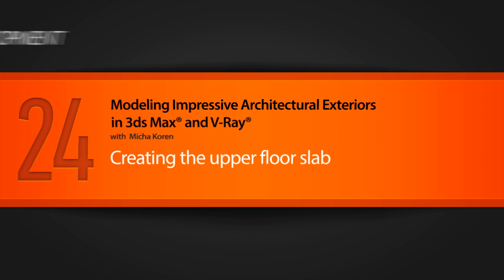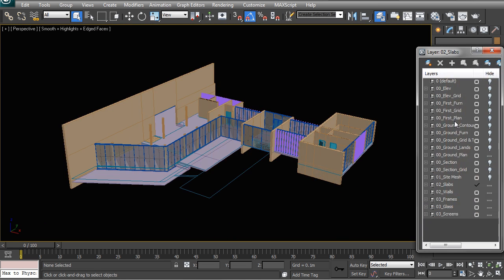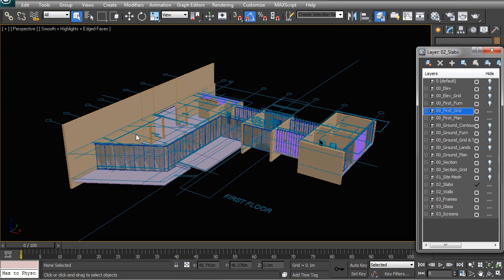In this lesson, we're going to be modeling the first floor slab from plan. Now, to get started, let's turn on the correct layer for the upper level, which is going to be called first plan. And we can also turn on the layer called first grid. This is the one that will have our height information so that we know at which height all of the finished floors are at.